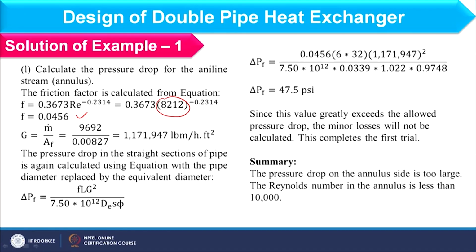If you recall the last slide, there we can obtain the flow area, and that flow area you can simply find through table B2, fine. All these values are given. So, here I am having the flow area, and corresponding to this, the G value you can obtain like this, and further we can find out the pressure drop in the straight pipe and the pressure drop